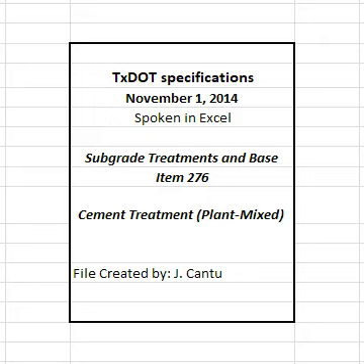The engineer may use project materials sampled from the plant or the quarry, and sampled by the engineer or the contractor, as determined by the engineer. Limit the amount of asphalt concrete pavement to no more than 50% of the mix unless otherwise shown on the plans or directed. Table 1.